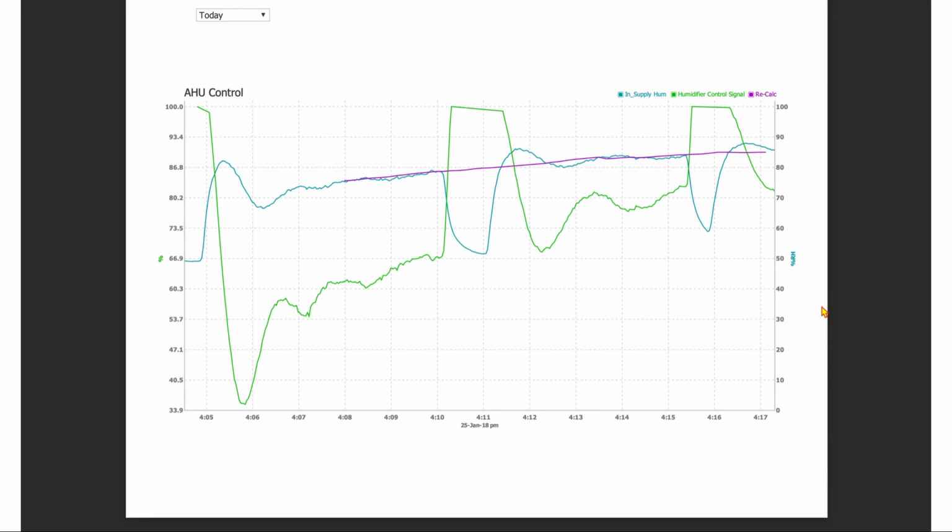And then we have other BMS applications where we need much finer levels of control. So it could be speed control for a pump, speed control of a fan in a ductwork, pressure control applications, or it could be a heating application. So it could be a heater in a space or a heater on a handling unit where we need to be able to control the heater based on an actuator or a valve, where we have a 0 to 100% control over a 0 to 10 volt signal. And in these sorts of applications, that's where we're going to use the PID loop to achieve that.